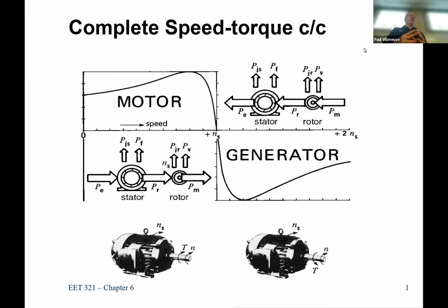So the doubly fed induction generators for many years were really adding to, if a fault occurred, it actually exacerbated the fault, because when the fault happens, you get a lot of current and then the voltage tanks. Now your doubly fed induction generators, all the wind turbines, they're not contributing anything. So the voltage drops even further and then your fault current drops. And so what you had is a very unreliable system.